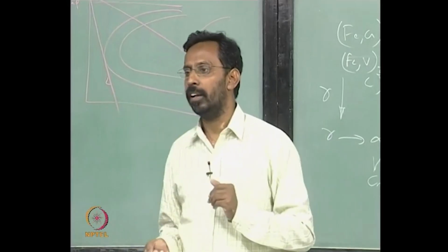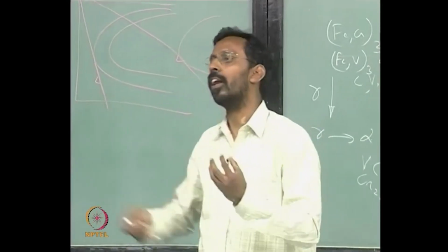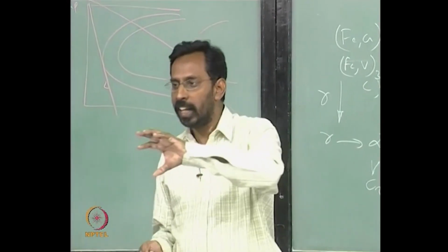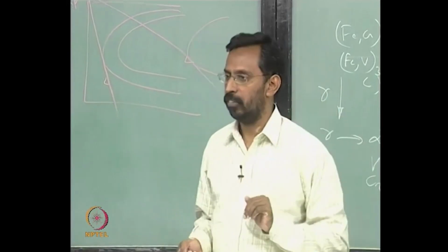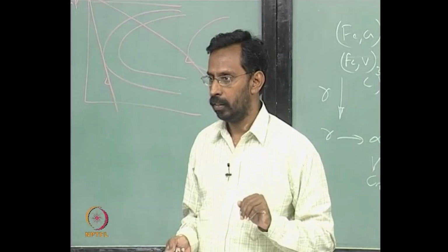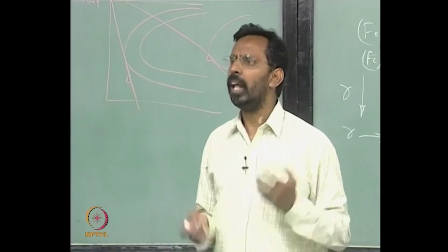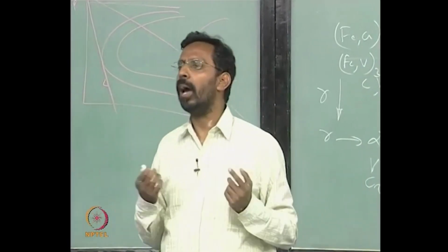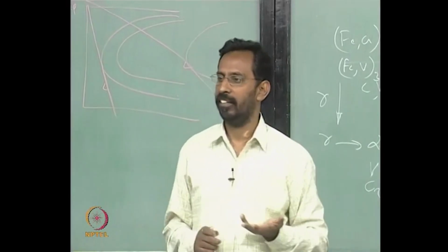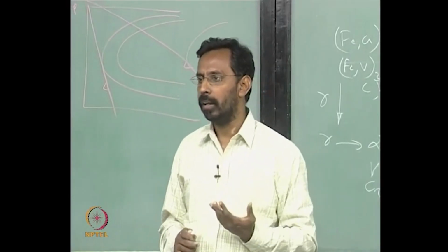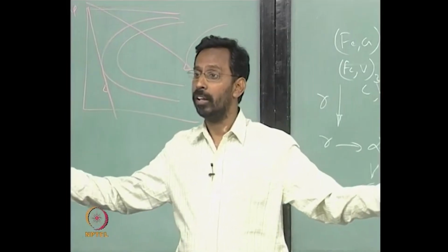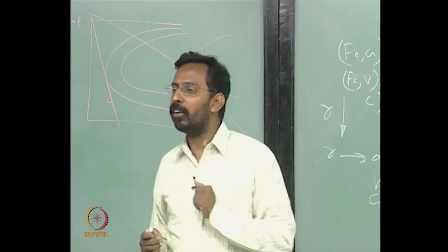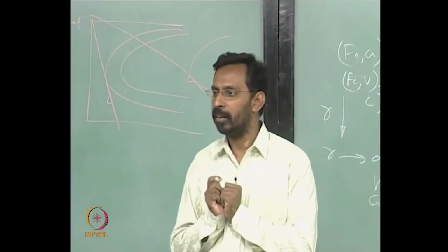If it is nitrogen present, it is present in the place where carbon is also present, that means either octahedral voids or tetrahedral voids. If it is nickel, let us say, it is sitting in the iron positions. Then, as you keep on adding elements with higher and higher size, the maximum solubility only decreases. The strain is more, and that is the reason why solubility is less. That is what we talked about when we talked about miscibility gap formation in a phase diagram.